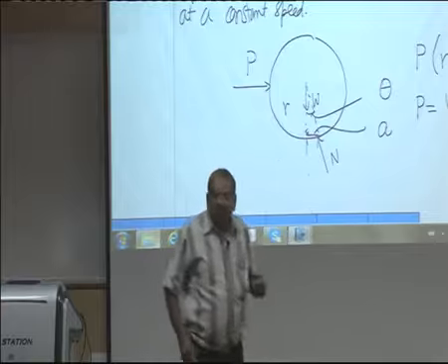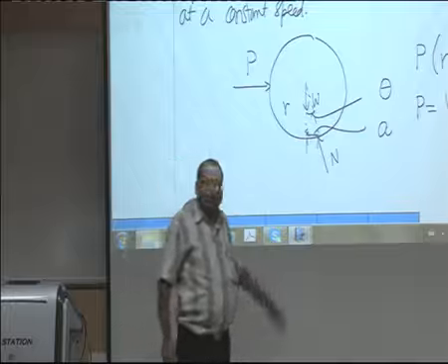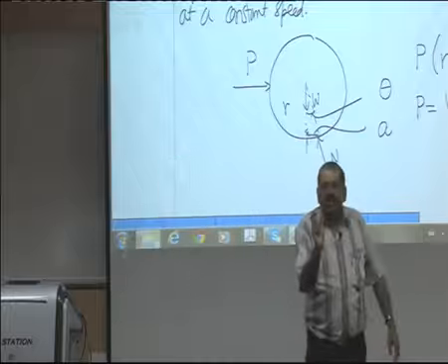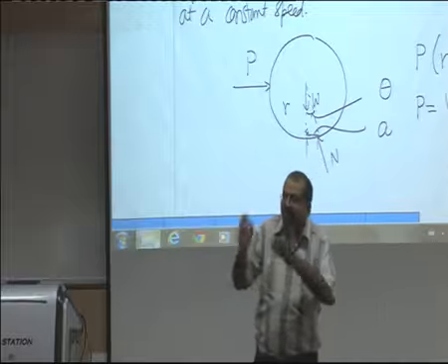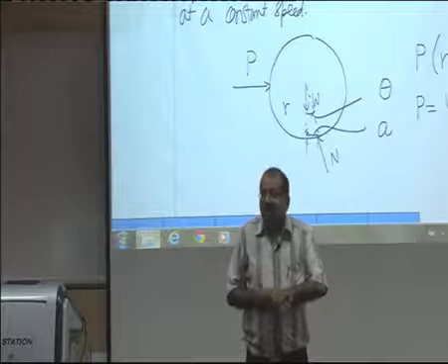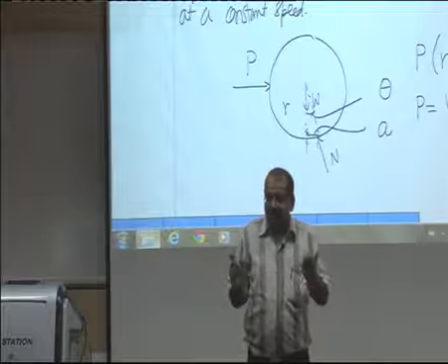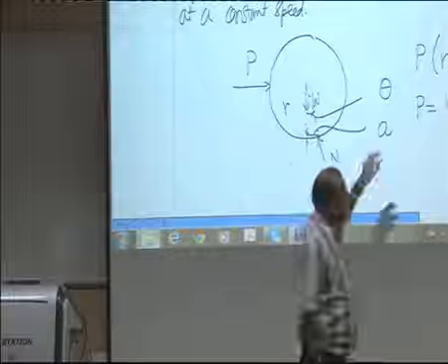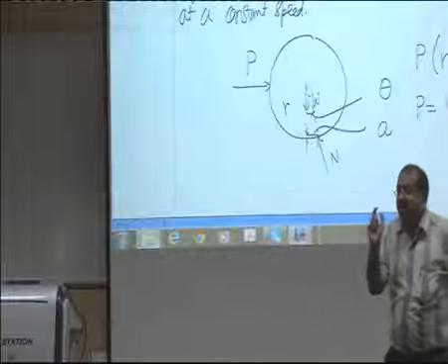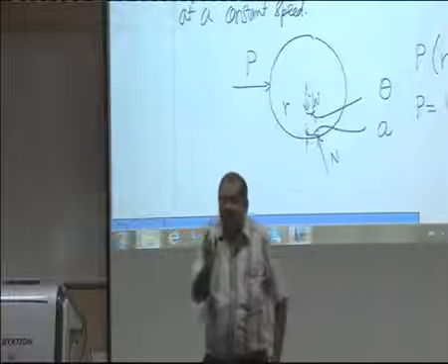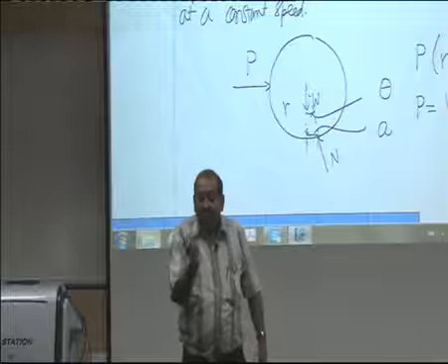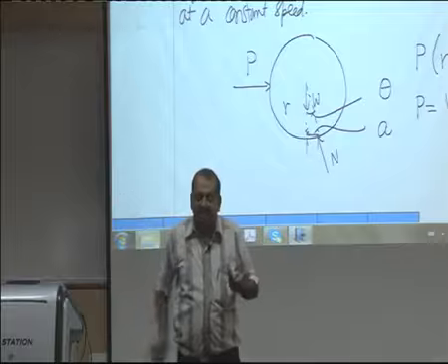Now, what you also find in the books is that instead of calling a/R the coefficient of friction, we call a the coefficient of friction. So the coefficient of rolling friction is written in terms of a dimensional quantity, the contact length, in meters or millimeters, whatever.